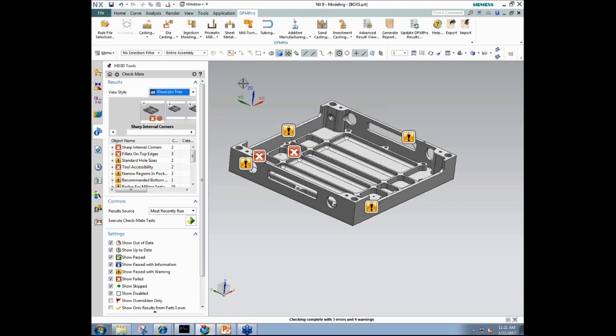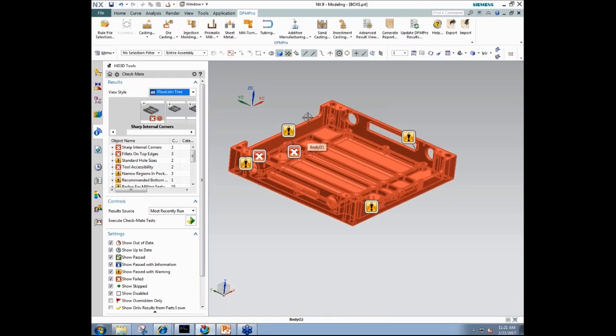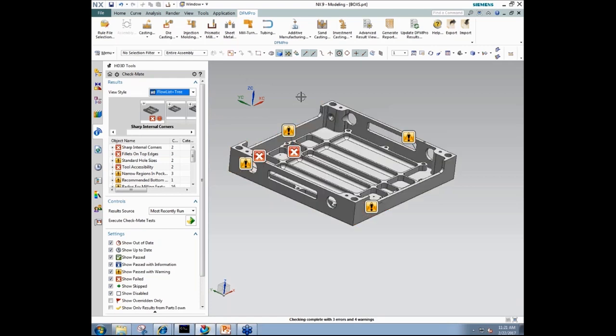These are identified as the manufacturing features, which will be machined using either a milling operation or a drilling operation, whatever the manufacturing process is. The way it works, it recognizes all these manufacturing features using our own patented feature recognition technology, and then the corresponding features, for example this pocket, will need to have some requirements. I have standard milling tools or milling cutters available.